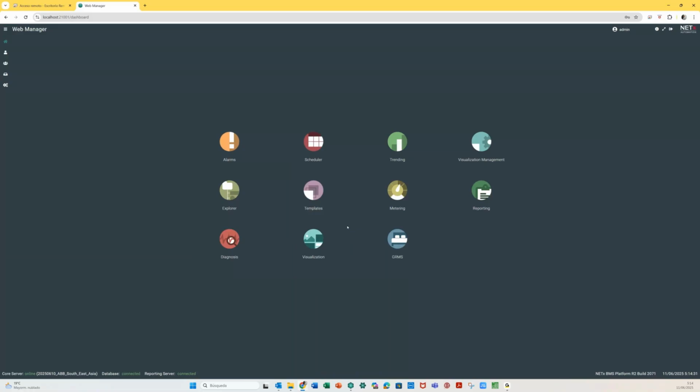Okay, so as you can see here, we will see alarms, we can have schedulers. So I would also say events, event generator. Events means time events. This is what we normally call a schedule, time events. But also here we can do conditional events that are very important for an integrator. The typical if this then do that, and it's really powerful and really simple to do these kind of things. Trendings is very important also to historize information. So we will see how to do these trendings.